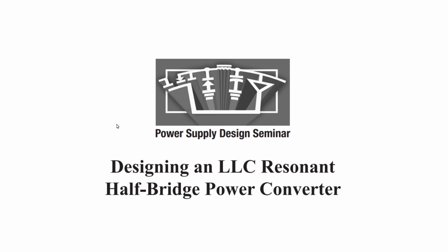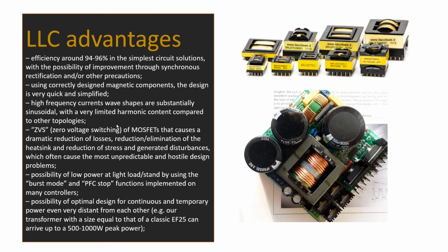LLC resonant switching mode power supply design. I did not find an exact definition of the abbreviation LLC. I guess that the meaning is 2 inductors and 1 capacitor. LLC resonant architecture is the absolute winner when we are talking about audio power amplifier power supplies. It is capable of working from almost no load to maximum performance. It has the highest efficiency among different switching mode power supply designs and the lowest electromagnetic interference noise.